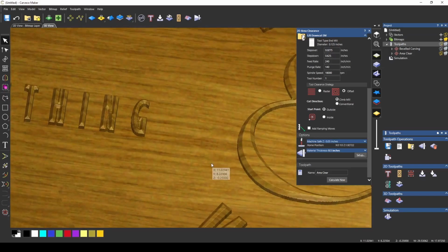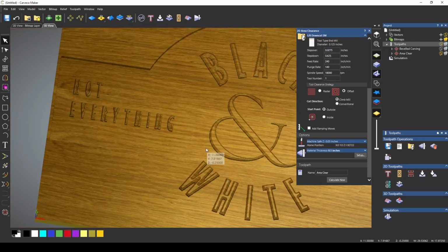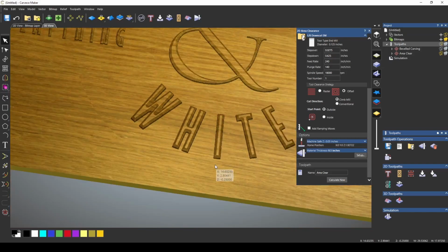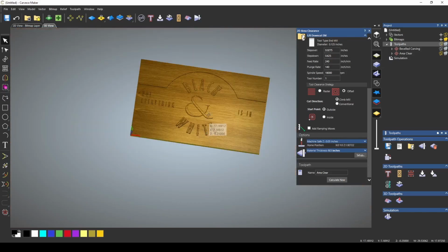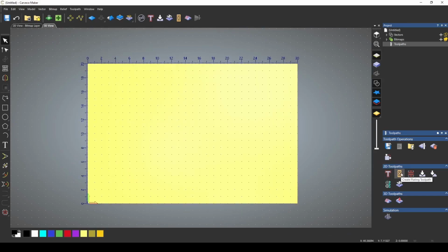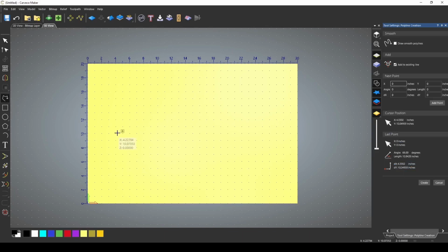This toolpath is overlooked by a lot of people. They probably don't really understand how the bevel toolpath works, but it can give you some really neat and interesting designs. And I'm just going to delete this. I'm going to go over the Fluting Toolpath. In order to show the Fluting Toolpath, I'm going to draw a vector.